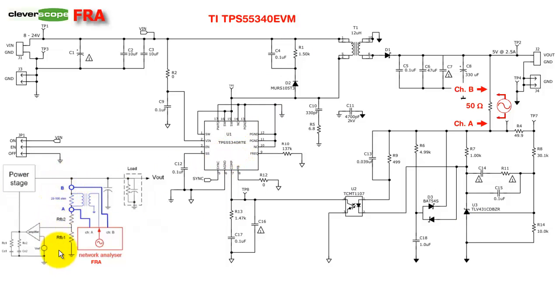The feedback system here are these components here, and there's a secondary loop, in fact, which goes for AC down here. Anyway, we need to inject the signal across here. Now, in the TI application note, they use the transformer, but we don't need to use a transformer. We can use the CS701.